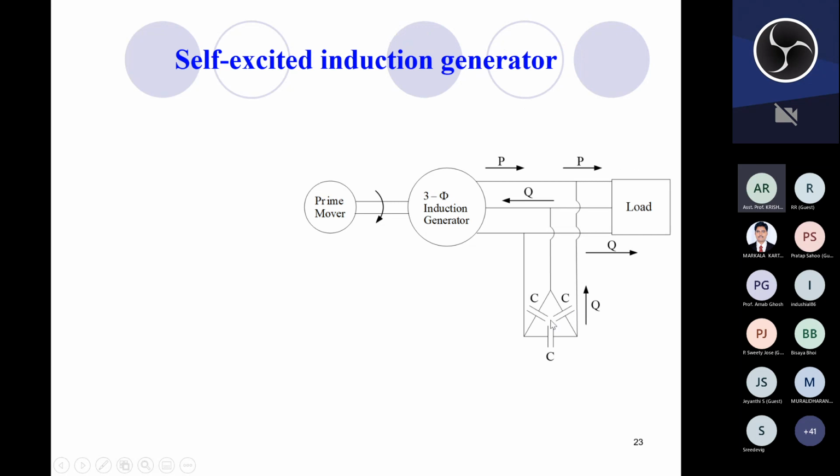And now the self excited induction generator. Here you can see it is not connected to the grid, it is directly connected to the load, and a bank of 3 capacitors is also connected to the stator terminals for the reactive power supply. Okay, this reactive power supplied by the capacitors is supplied to the induction generator to create the magnetic field, and also to the load, since the load can either be inductive or the normal situation is that the load is some kind of resistive inductive load. Okay, purely resistive loads are not always the situation, that is, we cannot always have a purely resistive load.